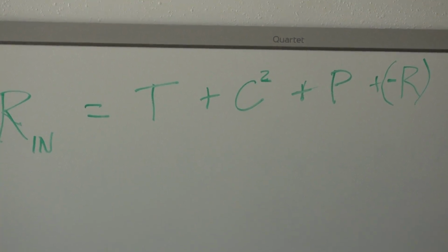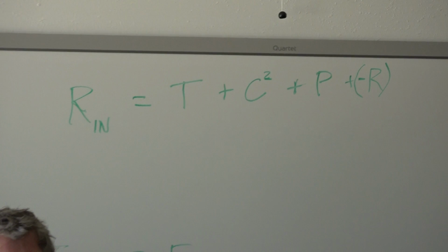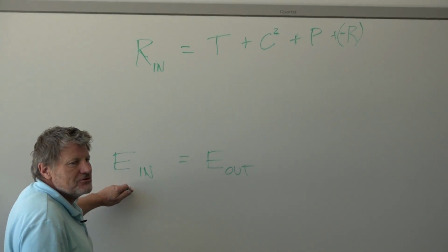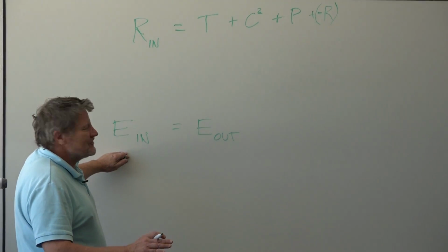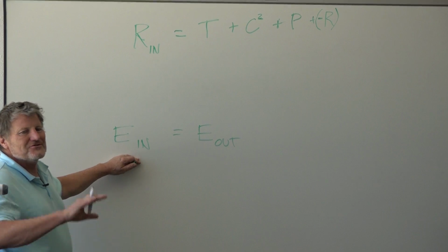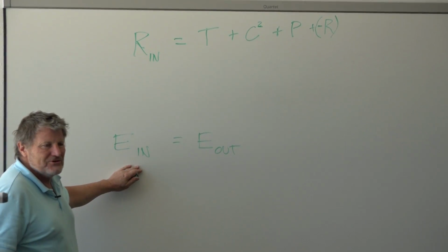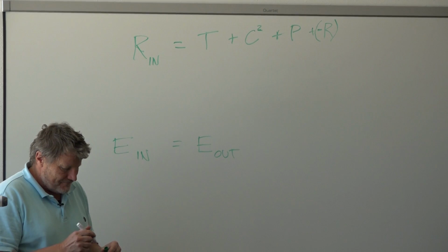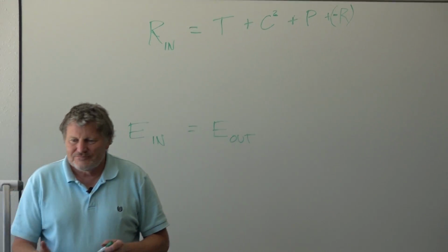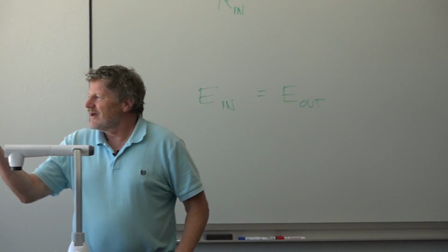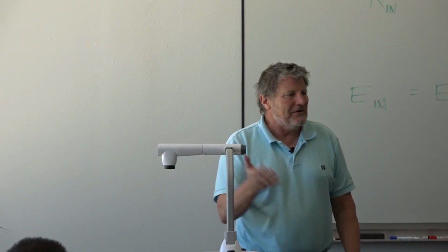But what happens when something changes temperature? Energy in equals energy out, but this balances over long time periods. If you take a black piece of metal and walk out in the sunlight and lay it out, it's going to get hotter. It's going to get hot fast, and this won't balance because it's heating up. Some of the energy is going in to change the temperature.